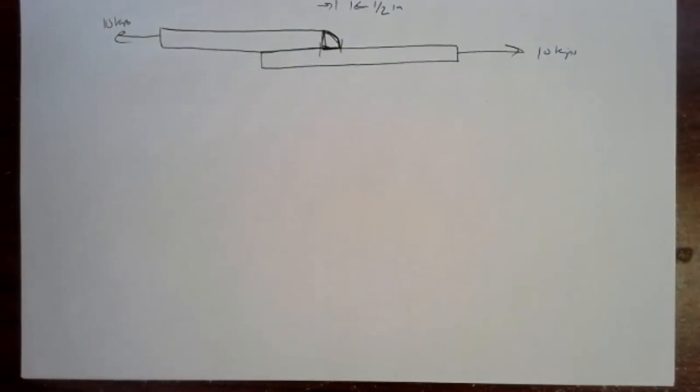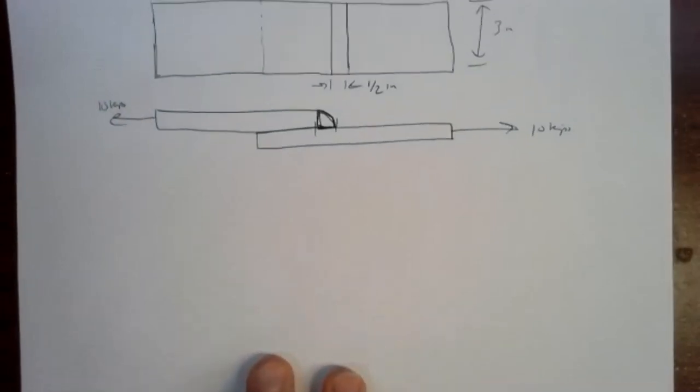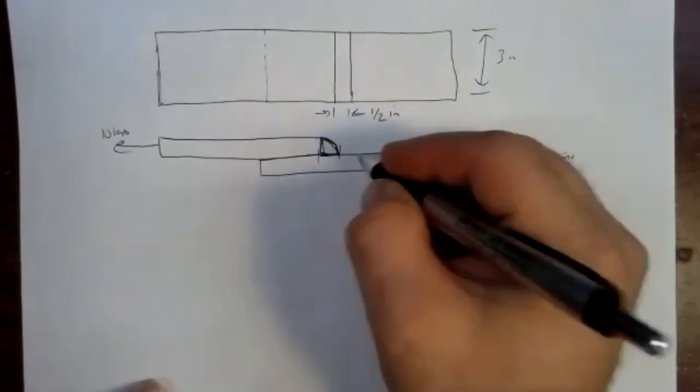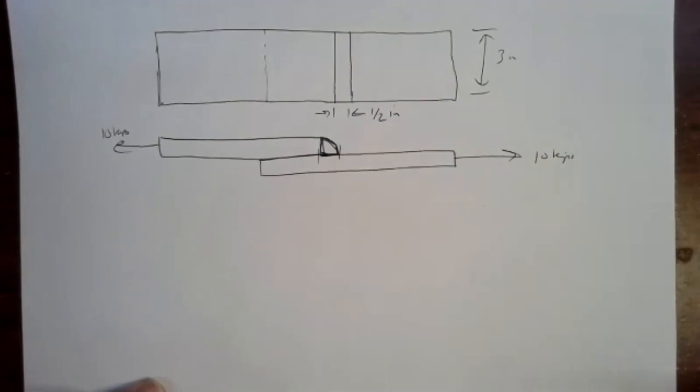It doesn't really matter what method, but stick is about the easiest when dealing with this kind of thing because with stick welding, you typically know from the stick you're using what the maximum shear stress is for that weld. It's usually encoded into the number for that stick. So if you're dealing with a 7,000 series stick, that's 70,000, 70 KSI typically. So you've got some idea of the maximum shear stress you can handle with that.